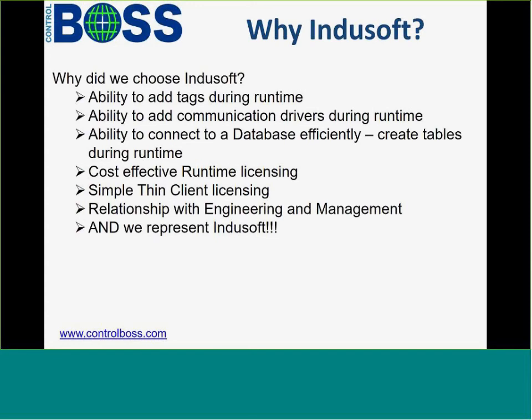So you see what we want, and why did we choose InduSoft to do this? So we really looked at this and said it's got to be a runtime environment. We really don't want the plant personnel to have to go in and edit a database or create an alarm or do anything where they have to shut the system down or add something to the system that could cause issues to a running system. So that needed some of InduSoft's key features, which are we can add tags at runtime. We can add communication drivers at runtime. The database connectivity of InduSoft allows us to now put all this data into a SQL database on the fly.